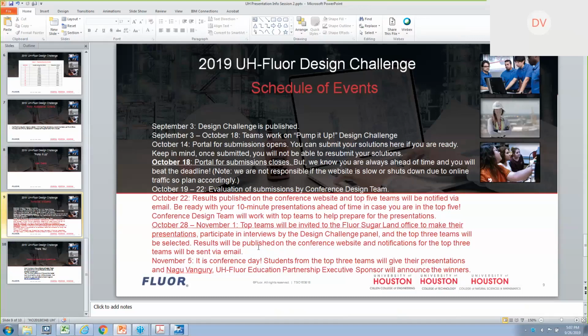What was also said was changing the pipe. For the original proposal that you'll submit, the 30-inch diameter pipe will stay the same. What will change is the wall thickness based on the pressures that will be identified from that pressure profile chart.